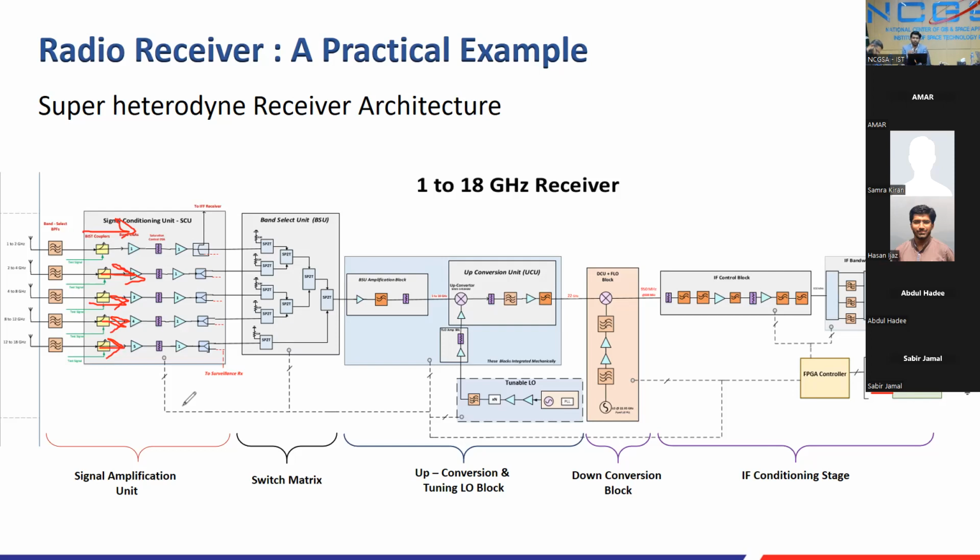So in this configuration, we borrowed that design originally from a Western design architecture, and we produce better results with our design scheme. You have dedicated antennas for that. You have band pass filters in the beginning. These are the stripline band pass filters. Then you have built-in test couplers. These couplers are directional couplers. There are two purposes for this coupler. One is you can inject test signals. For example, this receiver may be on an aircraft, a tower, or a remote site.